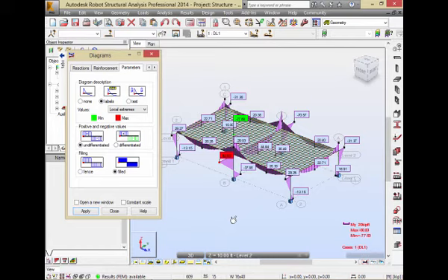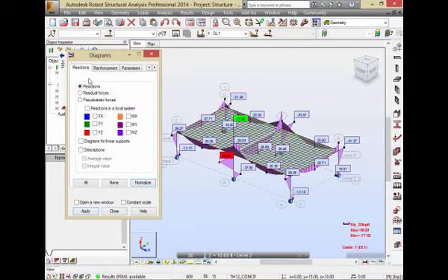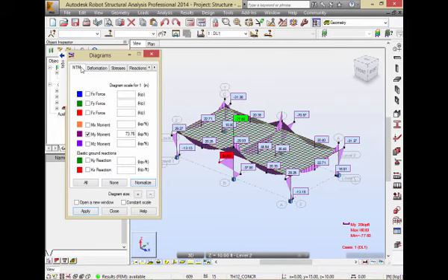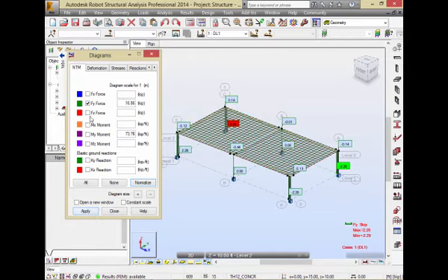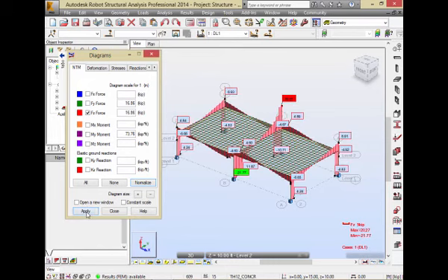We could do things like showing the reaction forces, or excuse me, the shear, or the moments. If I don't want to see that, I can go through and show, for example, just the shears instead. Oh, I didn't get that right. I'm so bad about the XYZs. Okay, there are the shear diagrams, showing us the different shear diagrams. Again, we can start sizing up our beams and doing our analysis based on that.